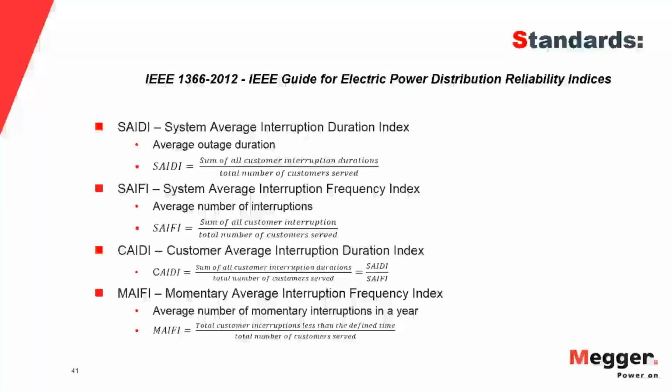So remember that using reclosers keeps customers powered more time. But if the recloser fails, then the operation of the recloser is not successful. And why does the recloser fail? Well, a lot of times because we didn't use the proper maintenance schedules and procedures with them.